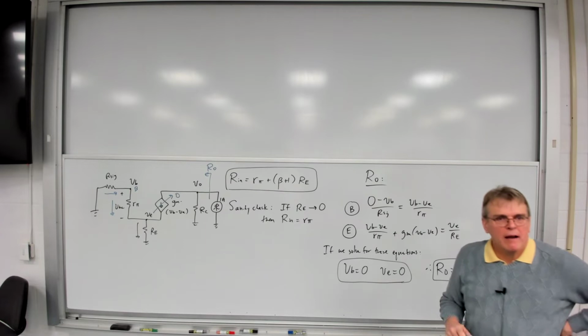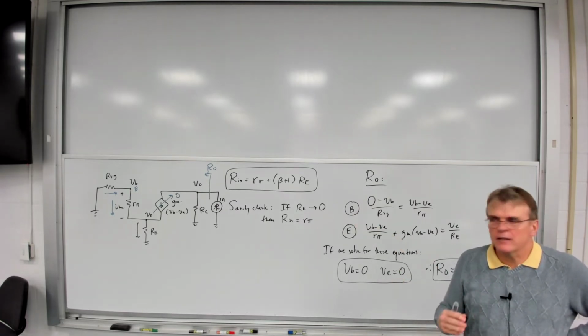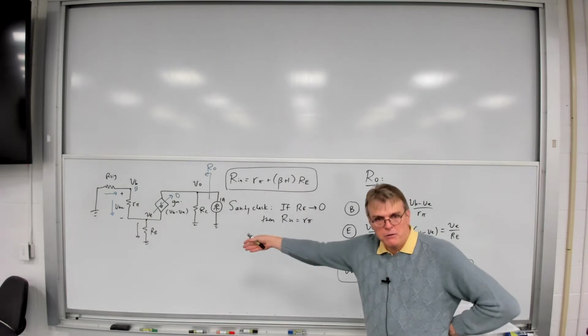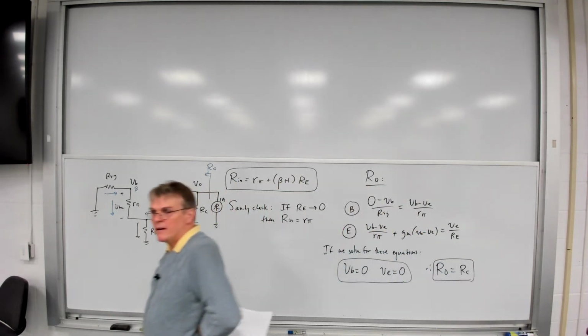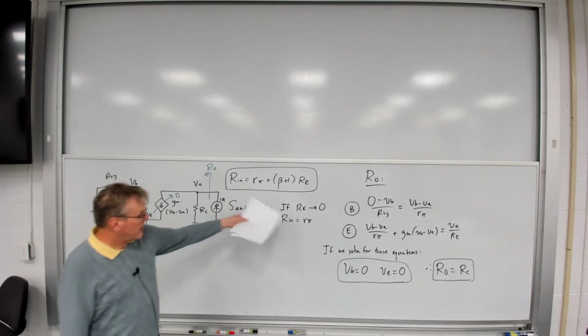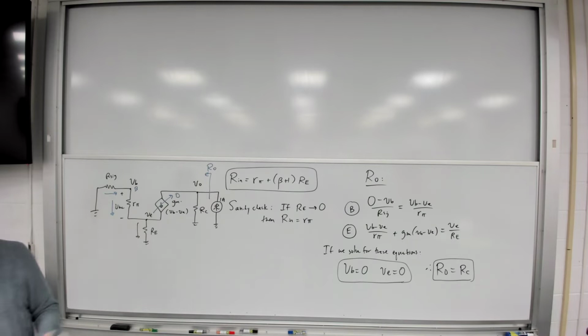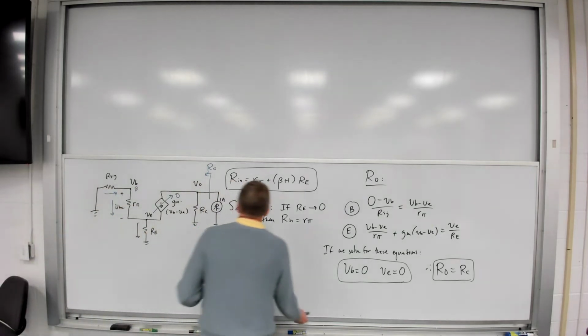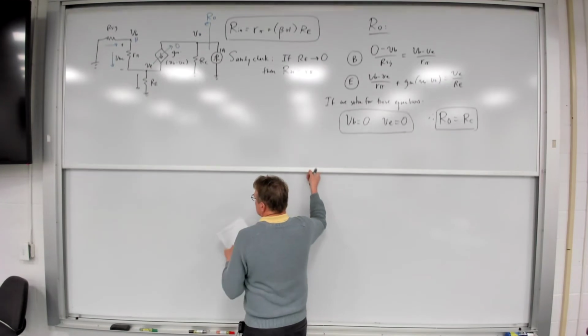All right, so common emitter amplifier with and without the emitter resistor. What changes significantly here? Well, obviously the gain goes down, as we've already talked about, but also the input resistance goes up. However, the output resistance stays pretty much the same, doesn't change. So now let's look at the common base amplifier.